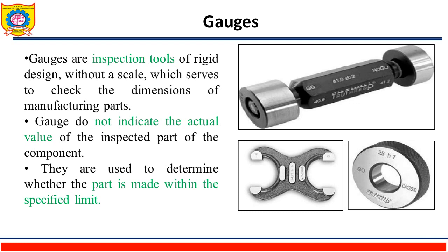In repetitive work, it is difficult to check the dimensions with precision instruments such as vernier caliper, micrometer, and other such instruments, which becomes much more uneconomical. So this conventional method of measurement needs a skilled operator and it also requires more time. In case of mass production, interchangeability also needs to be maintained at comparatively low cost. Hence, in order to overcome all these problems, gauges are used.